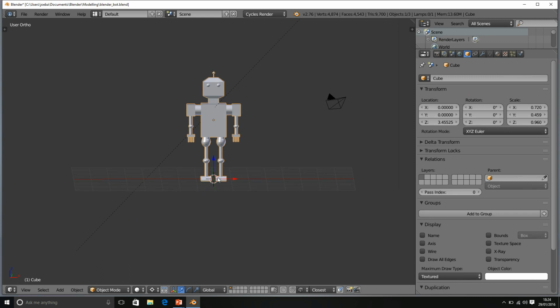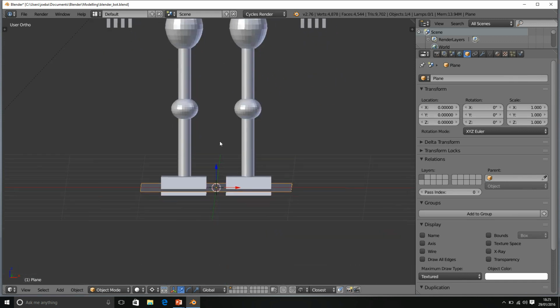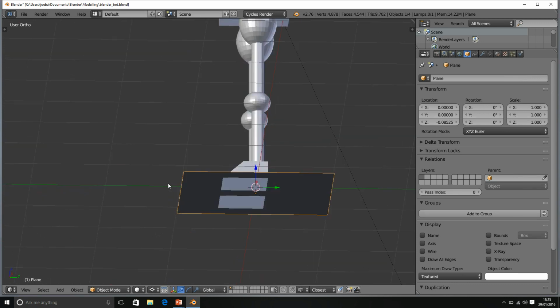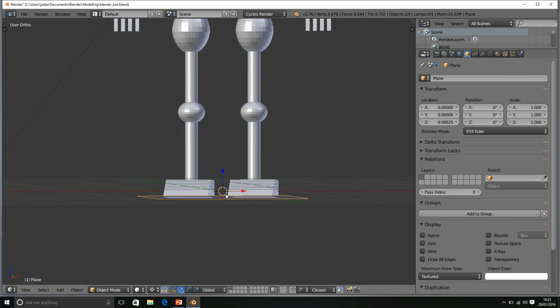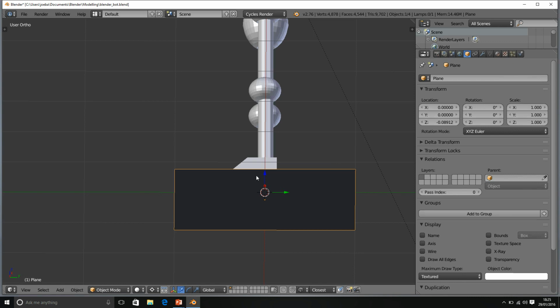Now I'm just going to create a scene. So I'm going to start by creating a plane underneath Blender bot. If we zoom in, we can see that the plane needs to be directly just underneath that. Looks perfect. There we go. So that's a perfect start, and perhaps just a tiny bit too high. Grab Z, and then press the down key on your keyboard just once, and enter. So you want it to get to the point where the bottom of the feet just become invisible through the plane,